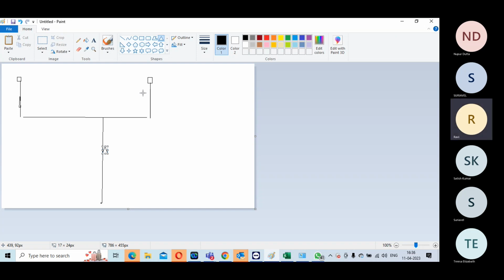Difference between single point CTS and multi-point CTS. Single point CTS is where you have only one clock point from where you build the entire main clock. Multi-point means you can have multiple sources from the top level, like a mesh. I am supplying one more clock pin at the center, everywhere I can supply. That's called multi-point CTS. Then the logic sitting closer to this, the flops, will have to connect to this. This whole algorithm itself is different.